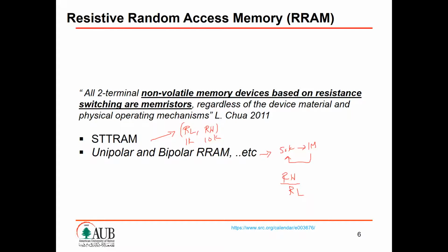And then there is also the property of, well, how robust is my design. This magnetic-based design, R low comes out as R low exactly, and R high comes out as R high exactly. Whereas here we have a distribution, so the 50 might reach 150, for example, and the 1 meg might drop to 300. So we need to design for these variations and take them into consideration.